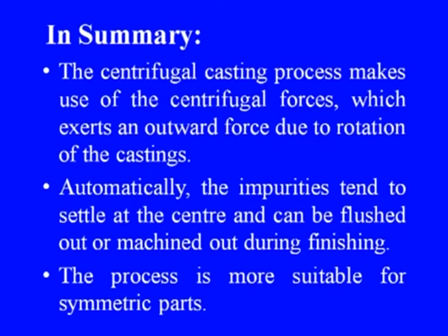Now, in summary, what have we learnt? The centrifugal casting process makes use of the centrifugal force, which exerts an outward force due to rotation of castings. Automatically, the impurities tend to settle at the center and can be flushed out or machined out during finishing. The process is more suitable for symmetric parts.